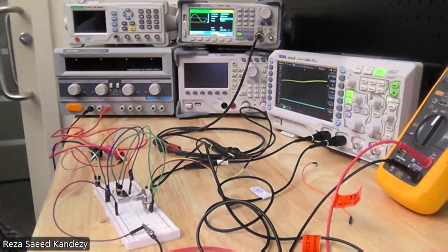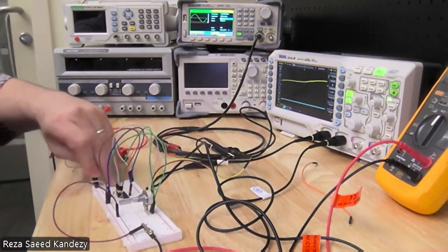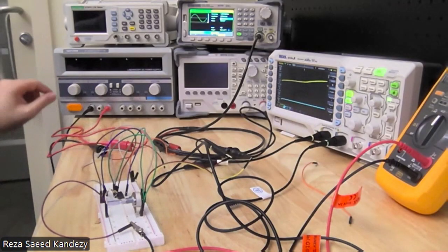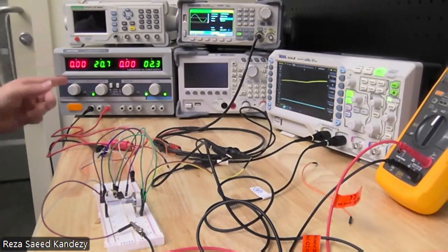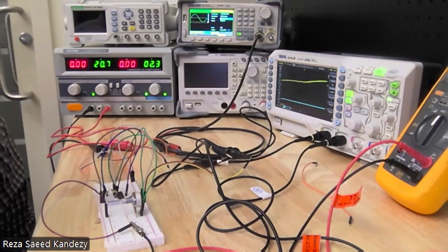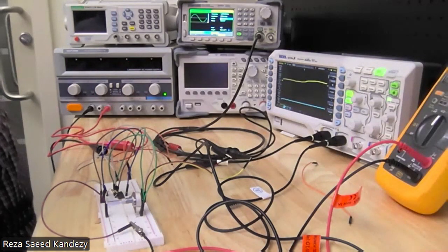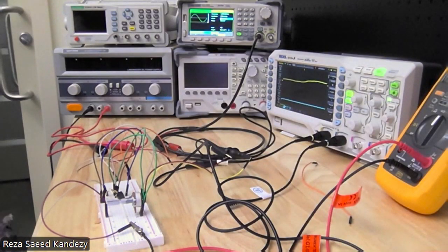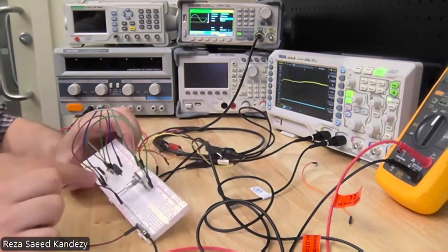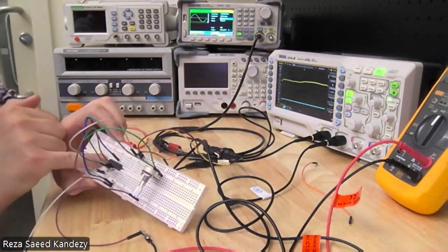Okay. So if you remember, let me disconnect the VCC before I start that. If you remember, we said the op amp range of the output voltage is VCC minus 1.5 volt. Okay, so what I have to do, now let's build that amplifier that we designed, and as you can see, I already connected the circuit. I have the LM324 here.